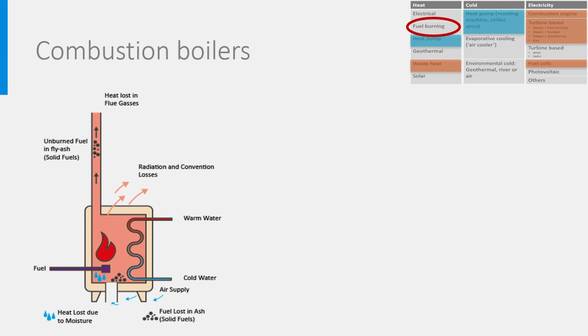In a condensing boiler, an additional heat exchanger is placed, see here above in the exhaust pipes for the fumes, which give now also their heat to the cold water. Not only the fumes give heat back, also and mainly the water vapor contained in the fumes. This water vapor contains a lot of latent energy that is released when the vapor is cooled down enough to condensate. Of course, these droplets of condensed water must be drained out of the boiler through an additional pipe. So, with this condensation, much more heat is recovered from the burning process.